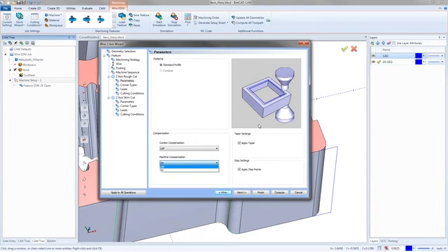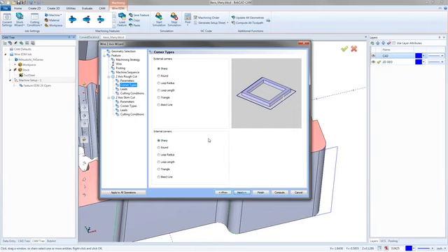So there we have it. Right here's our taper settings. If we want to apply taper on the rough pass, you'd say apply taper, which is what I'm going to do. If you wanted to leave it for the finish pass, you can uncheck the apply taper button here. Let the finish pass take care of it. Next, we then have the corner types again.